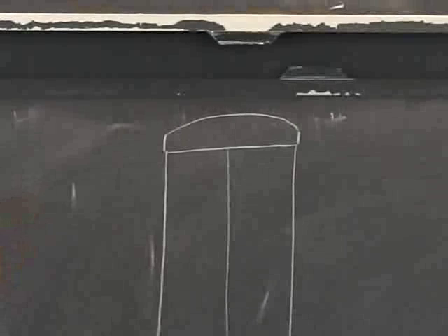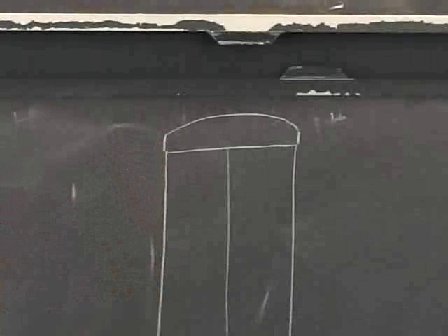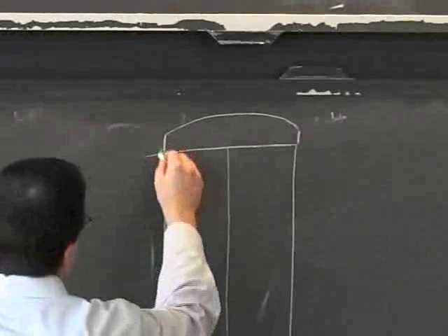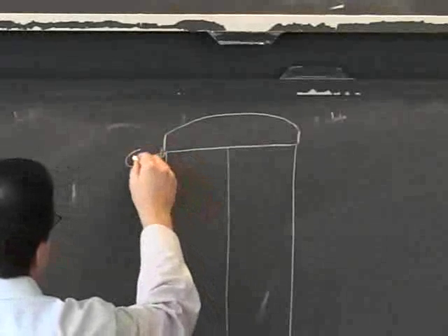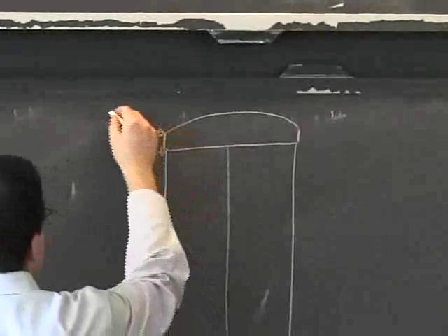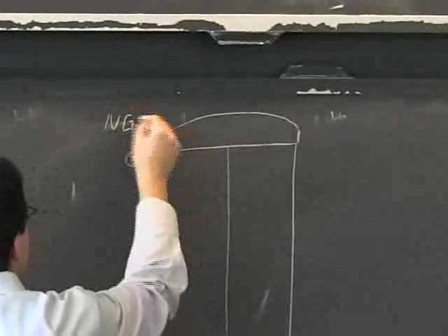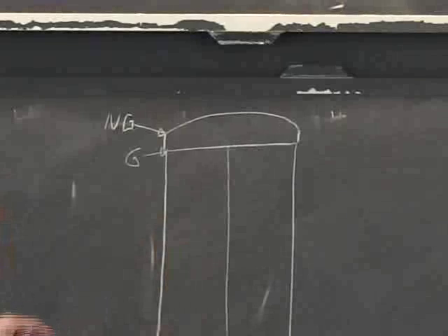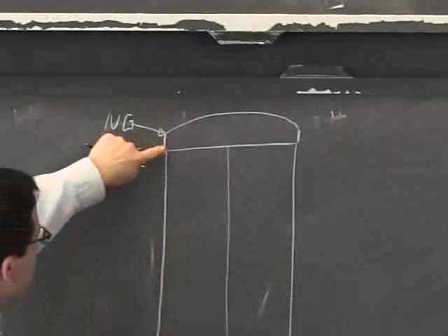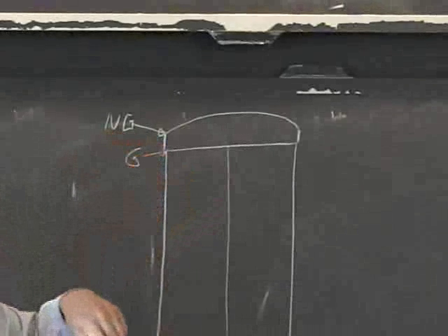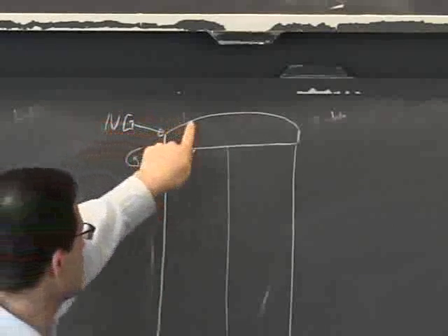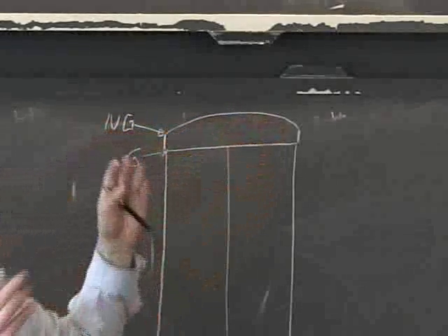It's not that hard to form that little flange. But the idea here is you put your weld at this location, so I'll mark it as good and here as not good. Because when you apply the pressure, over here there's no bending moment in the wall, whereas at the corner here you'll have a bending moment. This whole surface will try to expand.